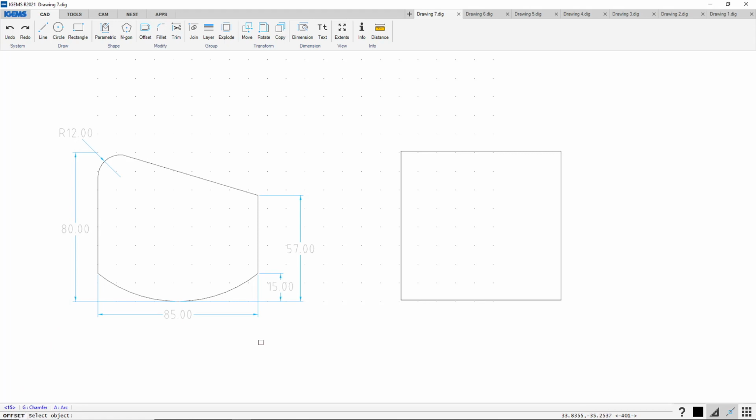So 15, select this line and move it, so either that side or that side, but we want to move it up, so click on this side. So now we have that, escape. I want to make this shape, because I know that the anchor point is 15 millimeters up, right here, and also the same there, and it's in the center at the bottom.